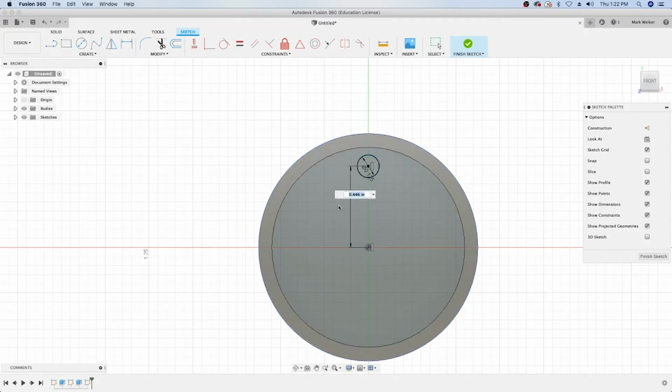One of the cool things about all of the CAD software we've been using is it can go ahead and do the calculations for us. So we know that if the diameter is 1.25, we can divide that by 2 to get the radius, because that's kind of the drawing that it's got. And then we can have it subtract 0.175. So that places it, and again, does the math. As long as you know what information you have and how you can modify it, you can make it a little easier.